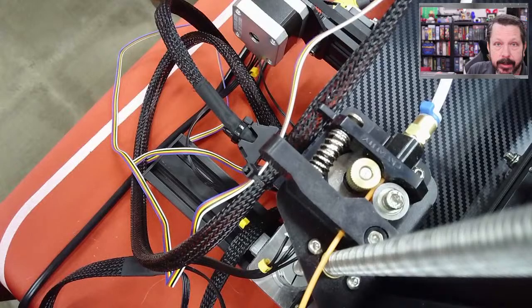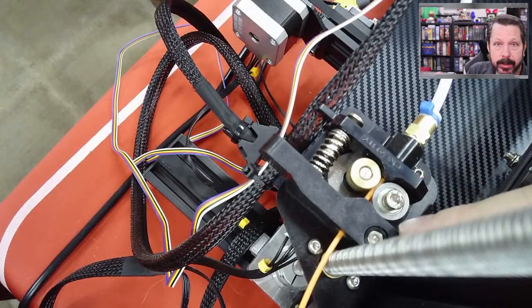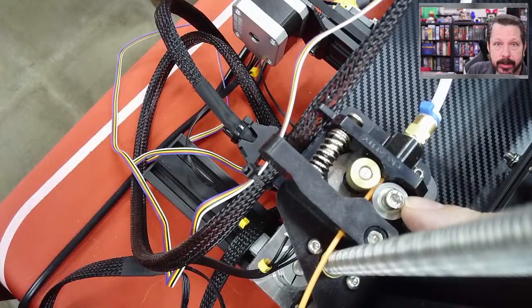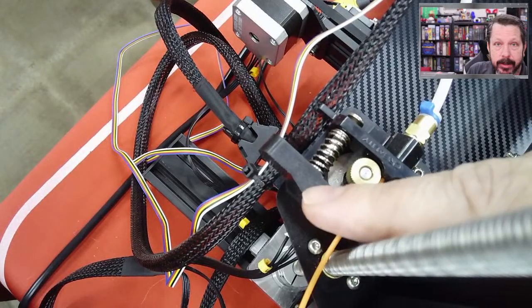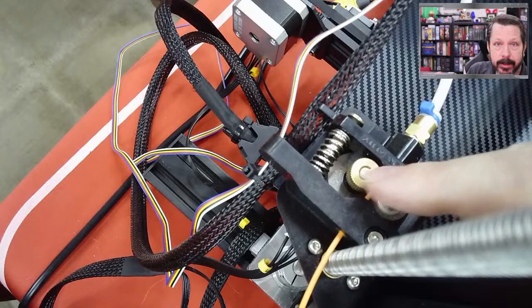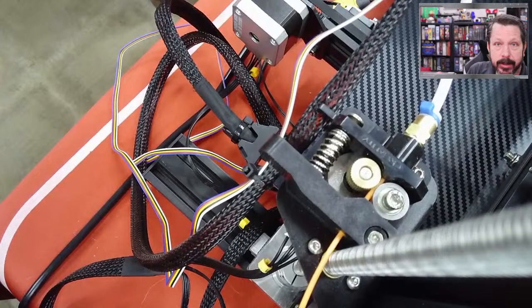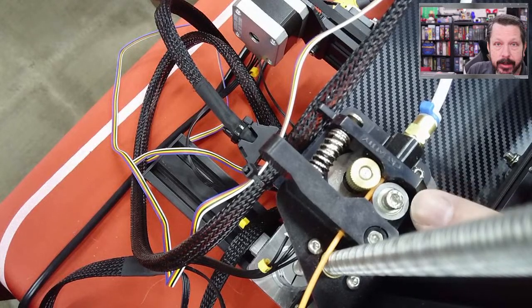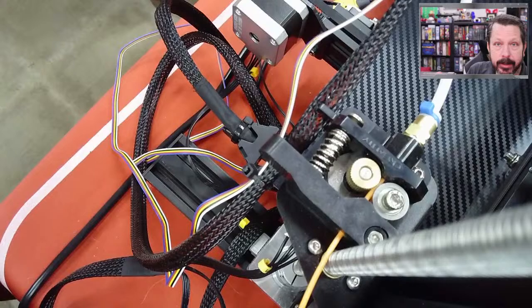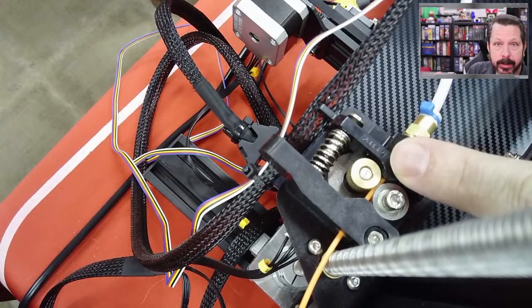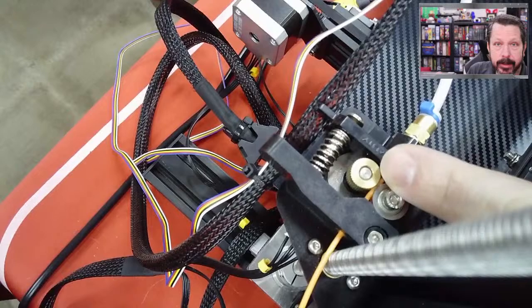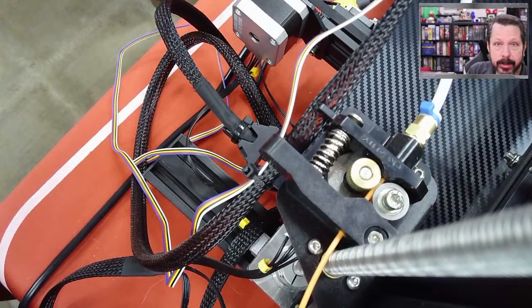This is a pinch roller setup. So this one right here on the existing setup is just kind of spring loaded and pinching the filament between the idler and the roller here. And we want to change both of those. So in our new one, they're both going to have to be changed. This one just comes off when you take the capstan, the plastic part off. This brass one is heat shrunk onto the shaft of the stepper motor, and you will not get it off by just pulling it off.